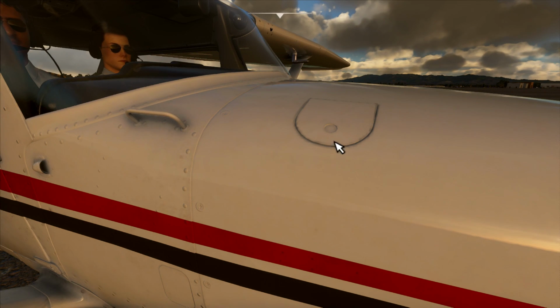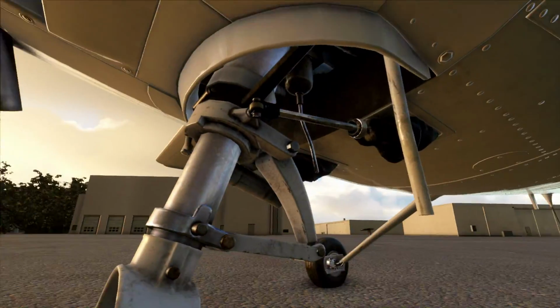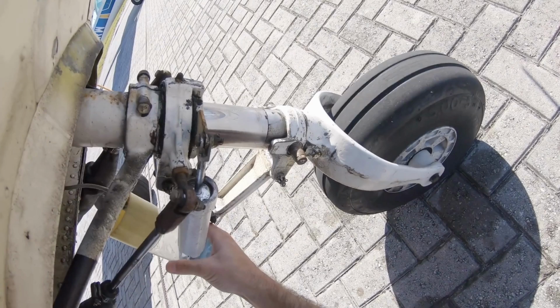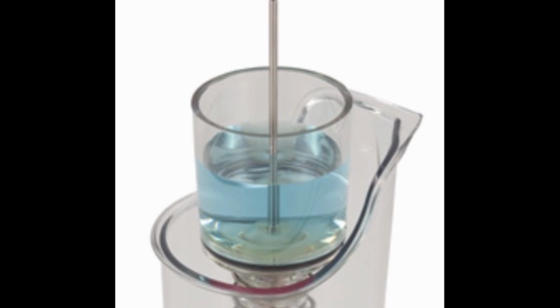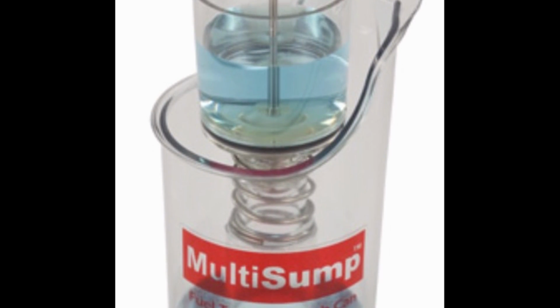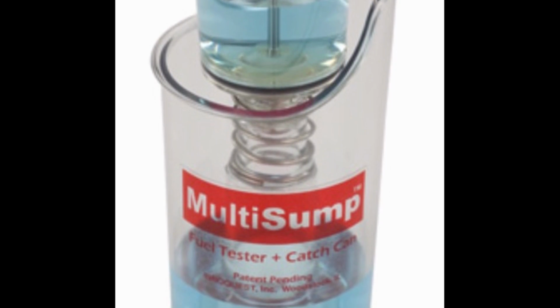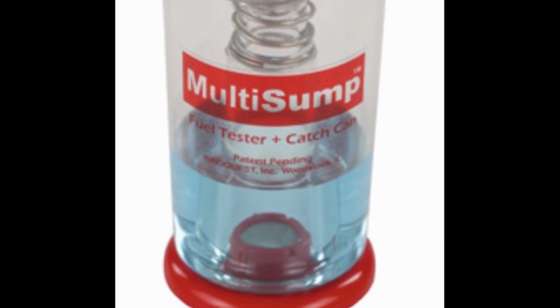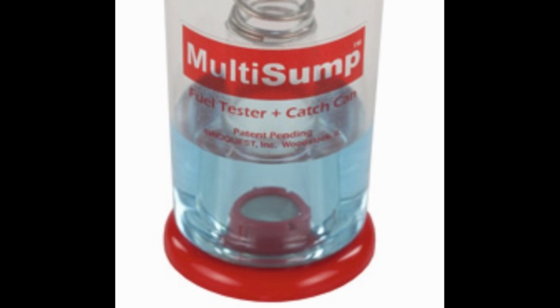At the cowl up front, we have this little door that the PIC will open, and there's a valve inside that the PIC will then operate while they place a fuel cup underneath this fuel drain line that's in the front landing gear well. Then they'll collect a sample of fuel. The PIC will verify the fuel type, and any water will appear in the fuel cup separated from the fuel, and if present, the PIC should take subsequent samples until no more moisture is present in the fuel cup. Any leftover fuel in the cup should be returned to the tank.